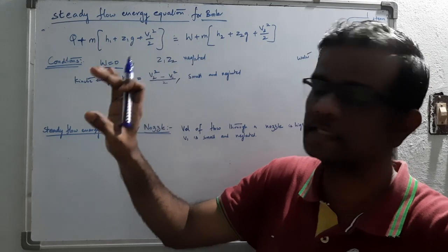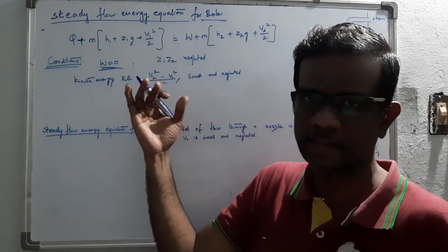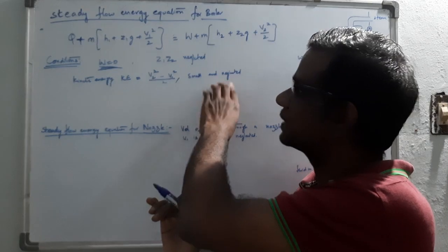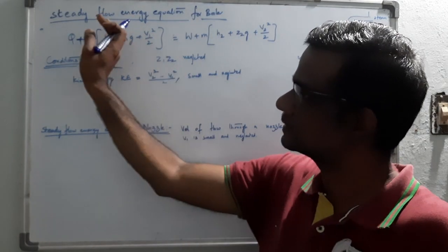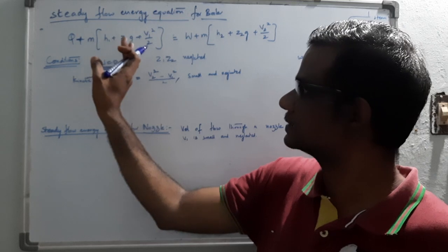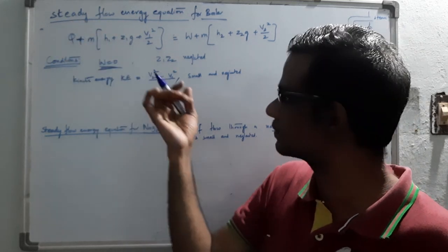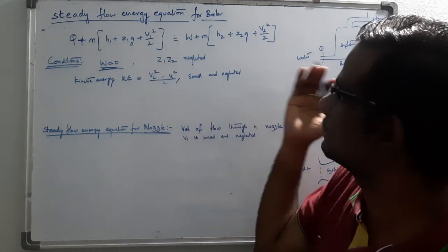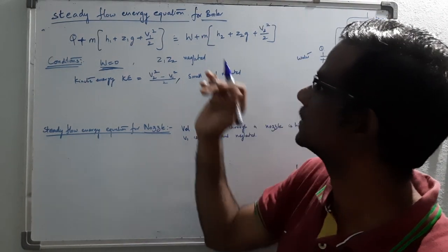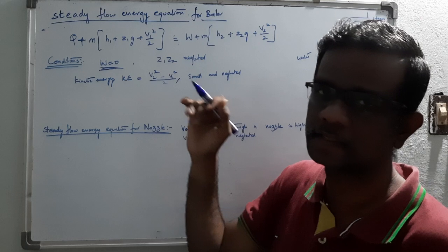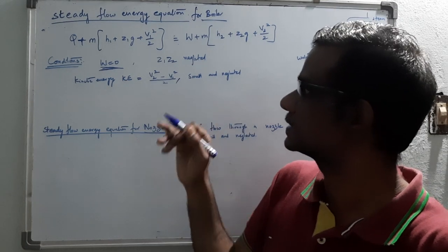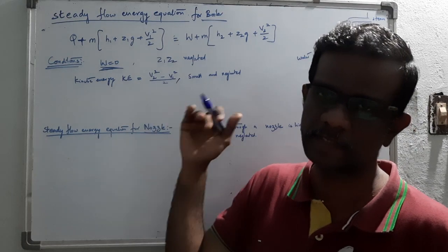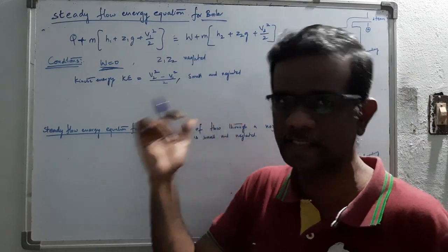For any problem regarding a boiler, identify the basic conditions, apply them and substitute in the general equation, and you will get one equation. If any problem comes, with the parameters of the steady flow energy equation for a boiler, such as h1 and h2, and you are asked to find the heat, you directly apply that equation.